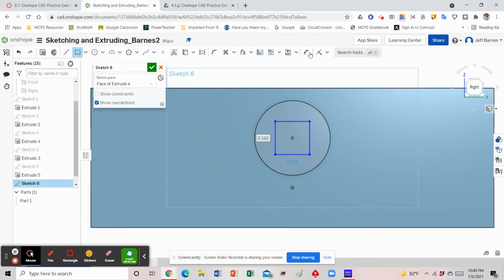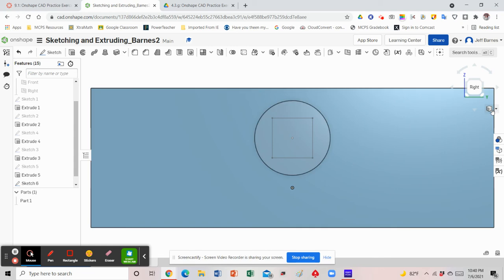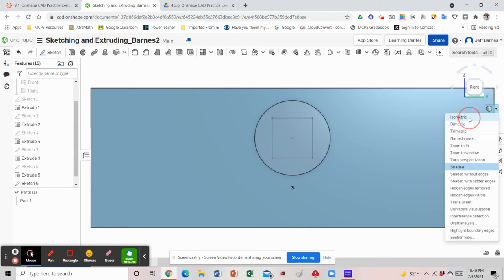So I'm going to go ahead and dimension. Make that 0.2. Enter. And it looks like it might have also done the other sides, but I'll just double check. Oh no, a little bit smaller there. 0.2, enter. So we just make sure we have 2 perpendicular sides, dimension for our square, and they're both 0.2 inches. And then we finish our sketch. Go ahead back to isometric view.